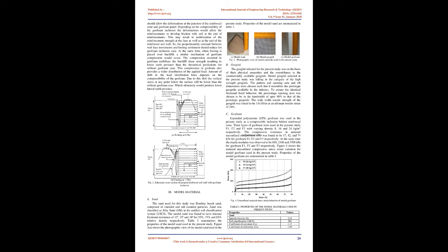In accordance with the above, the present study demonstrates small-scale model tests on geogrid reinforced soil wall models subjected to a 0.23 H wide strip loading over the reinforced fill and backfill, with and without geofoam inclusion. Reinforcement type, length, and spacing were kept constant for all the model tests. Parameters varied were the placement position of geofoam, geofoam density, and geofoam thickness. 2. Motivation behind the present study.